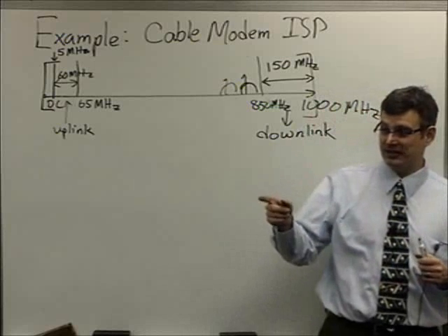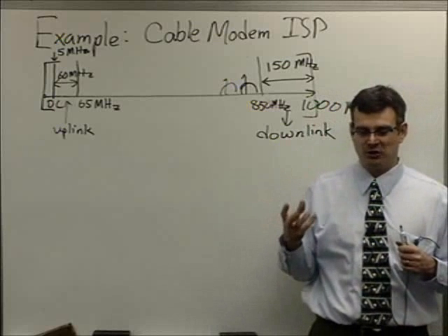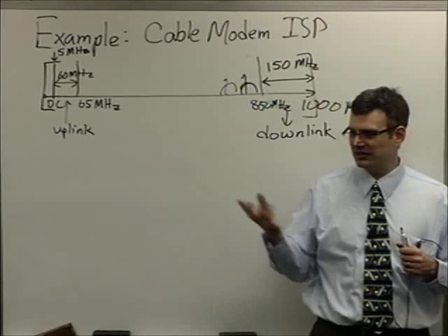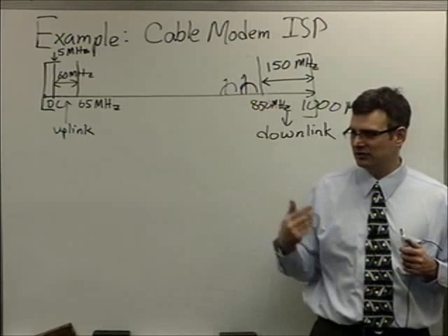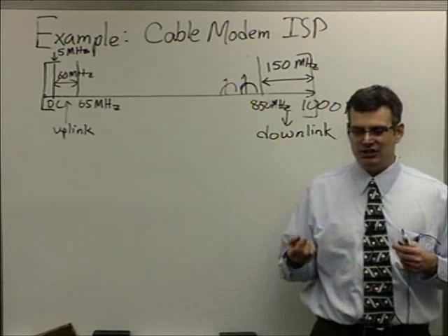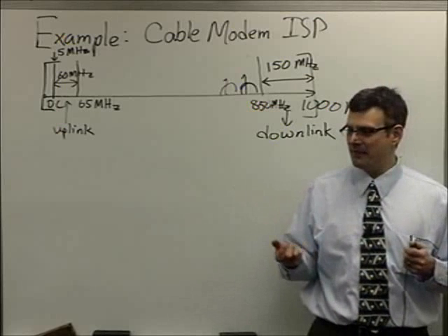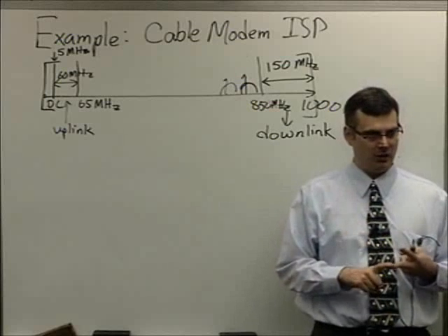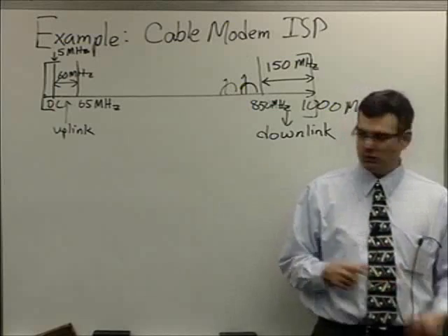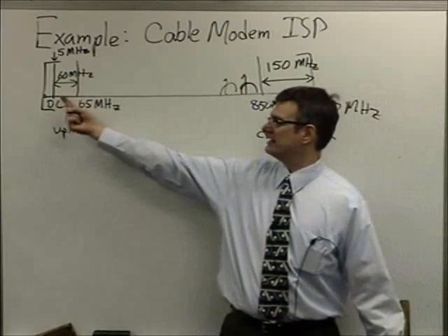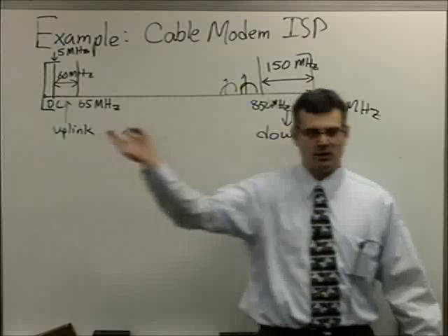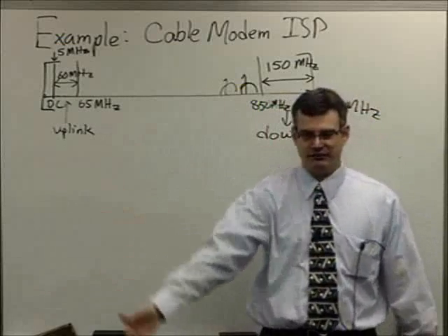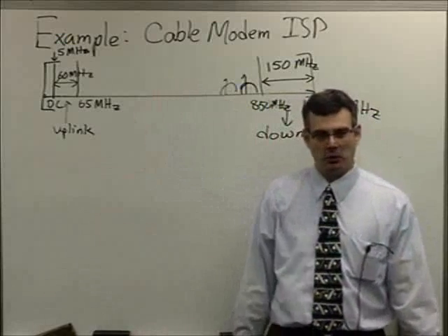Well, generally speaking, the little set-top devices on top of your television or behind your computer, that's basically your cable modem. You don't want to put expensive high-powered amplifiers in them because it makes the device cost more. It sucks a lot of power. Probably risk more home fires. You want a low-power device to send signals and still make it down a couple hundred meters of cable length to get to the next regenerative repeater, the next amplifier in your network.